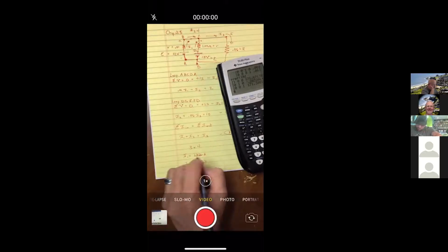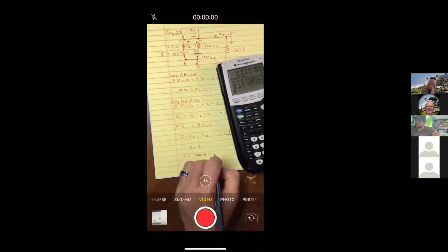So maybe here I should have put 171.7, because then what's going through the starter motor is 171.4. So a little bit has come off of the good battery and is charging the battery, not by much. But the dead battery is kind of hurting our ability to start the car here. It's not even helping it.